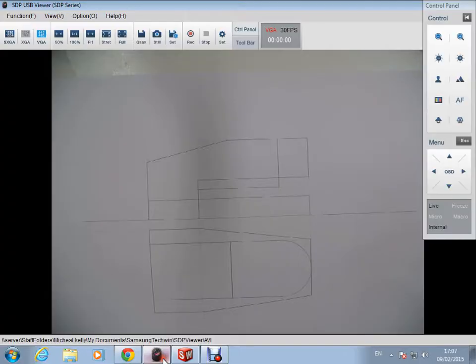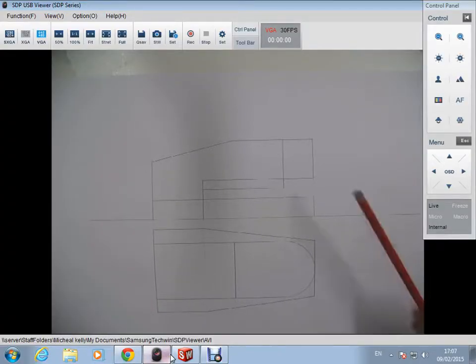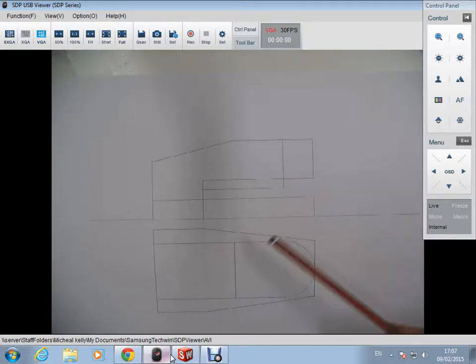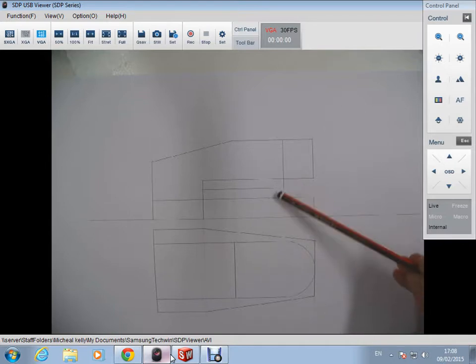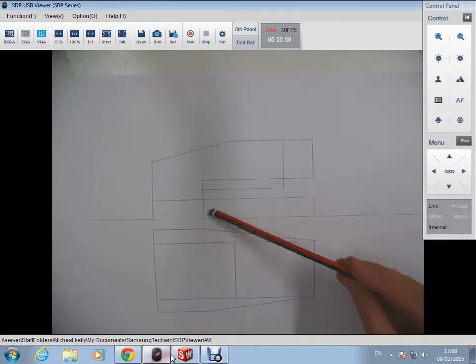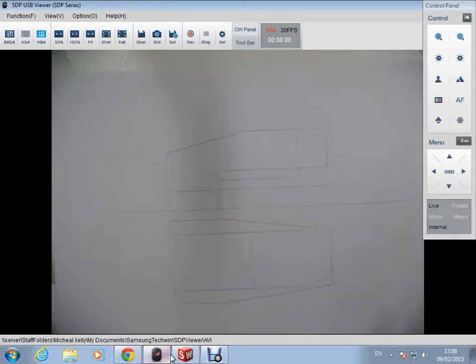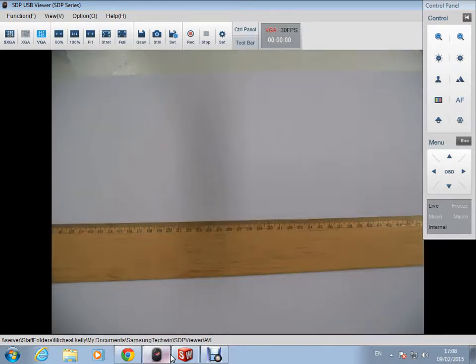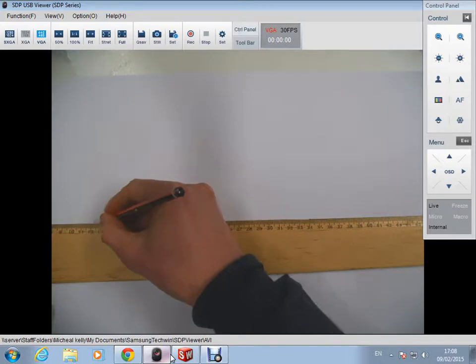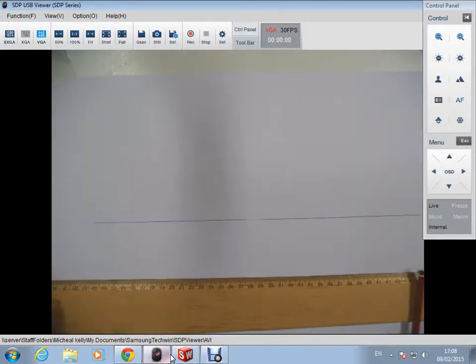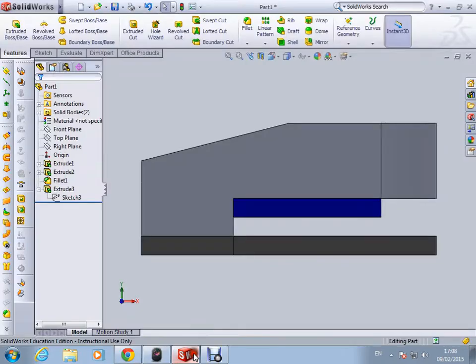So I have a completed drawing done here. So your completed elevation should look something like that, and your plan will be projected from your elevation, meaning that all of your vertical distances will be taken down from your elevation to your plan. So to start this question, I'm going to draw a horizontal line in the middle of my page, which will represent the XY line, which is in our 3D model the line that our elevation sits on top of. The plan will be the line underneath this.